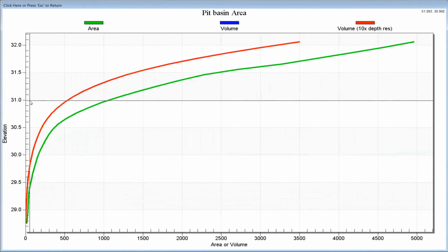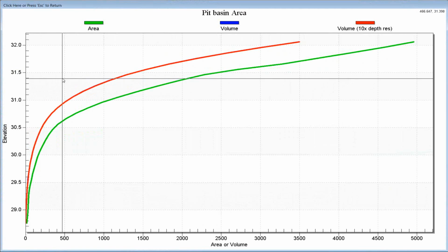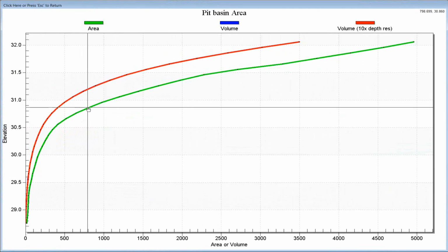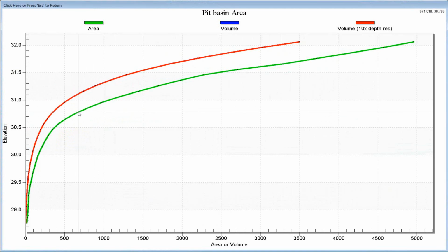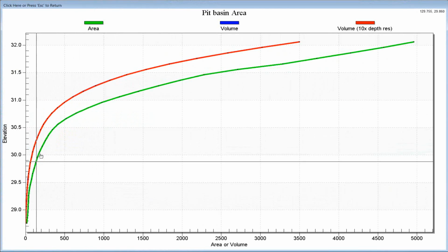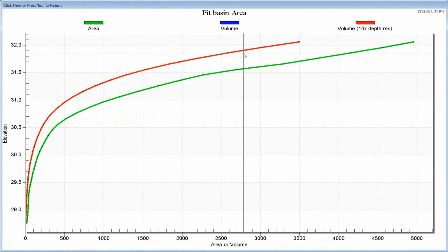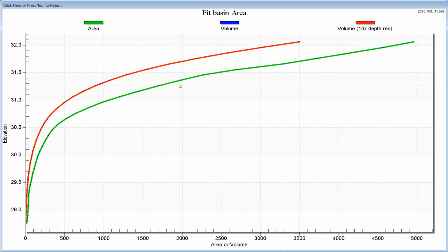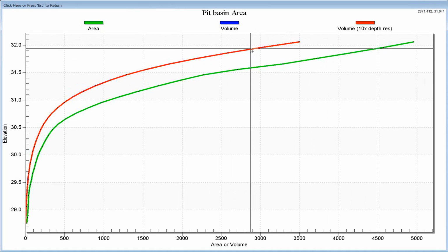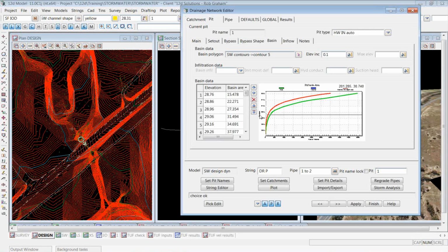So what happens is we do an interpolation. Let me go back here and mark the data points. The first time we did this, we calculated the areas every 0.1 of a meter. So what we do then is repeat the calcs and interpolate the areas every 1/10 of that and recalculate the volumes. So in this case, hopefully you feel somewhat more comfortable that the approximation is valid, as you can't even see the difference between the blue and the red. They're right on top of each other. So once we have this upstream storage volume, we're ready to go and run our analysis.